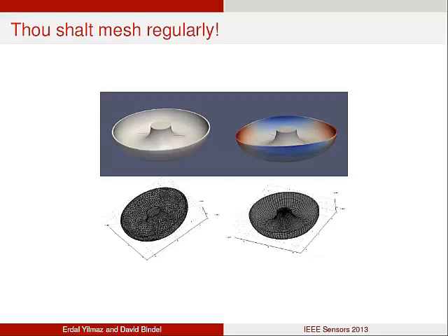And remember, this is for the perfect case. Rather than using this unstructured mesh, if we use a structured mesh by creating quad elements on the cross-section and revolving it around the symmetry axis, then this problem partially goes away. We end up having modes very close to each other, maybe a millihertz type of difference in this case. But this mesh that we created actually is not good for every m and p value.